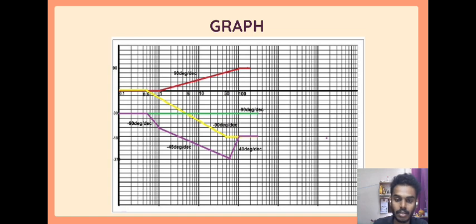The zero causes a slight bump near omega equals 10, but can't overcome the dominant pole effect. The final value is negative 180, which has important implications for system stability and performance.